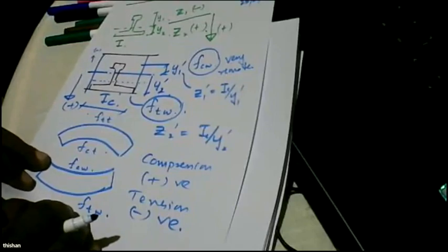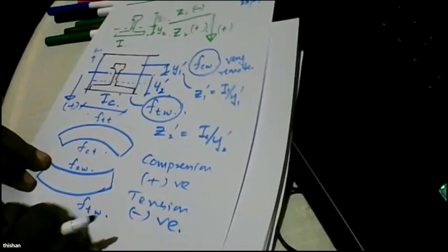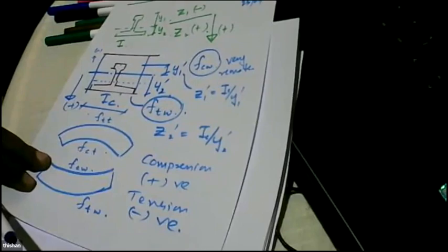The reason is by adding concrete, we are going to make it a bigger section. It's a composite section. So when you are looking at the fibers, we have to look at the relevant fibers of the precast section, right? We are not extremely worried about the concrete we are going to place subsequently, because we can always adjust the strength of that particular concrete, right?